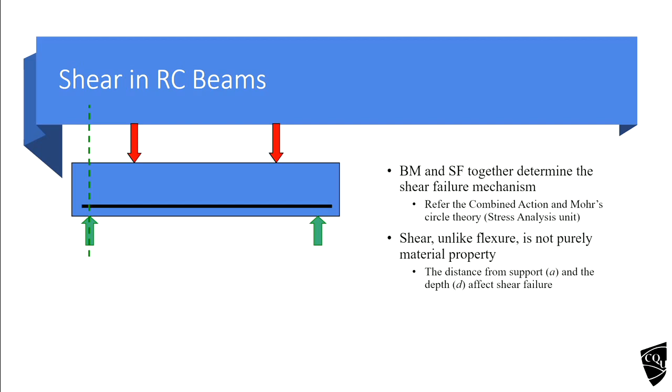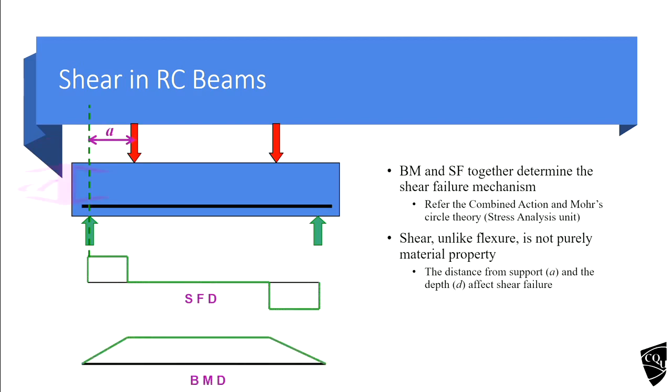So what is the shear? The shear crack generally starts near the support, okay, where you have a large shear force. So we need to provide some reinforcement. Sometimes we need it, sometimes we don't. So how do we know whether we need the shear reinforcement or not?